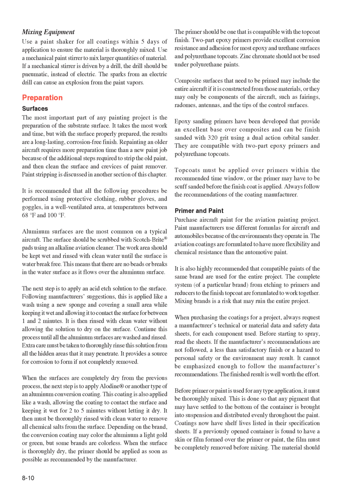Primer and paint. Purchase aircraft paint for the aviation painting project. Paint manufacturers use different formulas for aircraft and automobiles because of the environments they operate in. The aviation coatings are formulated to have more flexibility and chemical resistance than the automotive paint. It is also highly recommended that compatible paints of the same brand are used for the entire project. The complete system, of a particular brand, from etching to primers and reducers to the finished topcoat, are formulated to work together. Mixing brands is a risk that may ruin the entire project.